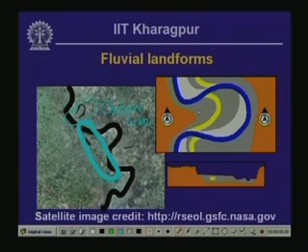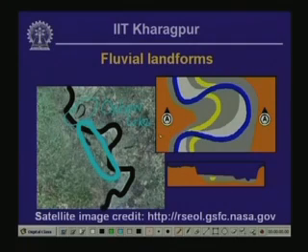The blue line is basically the existing water course, and the gray shading indicates the floodplain underlain by silts. The yellow line indicates river channels that are no longer active, and these yellow channels are underlain by sands, sandy soils. The area on either side of the gray shaded area indicates the terrace or uplands, that is, the lateral extent of the floodplain.